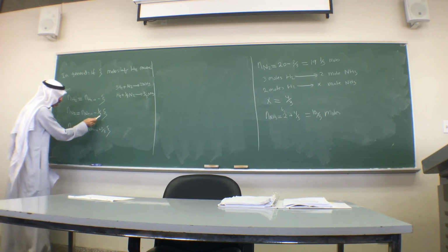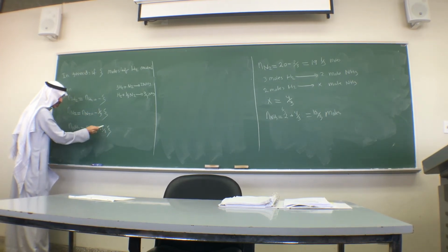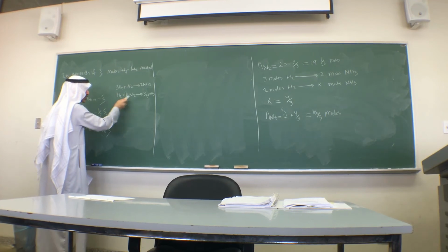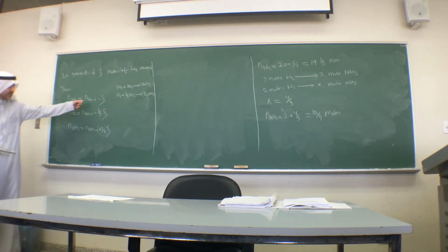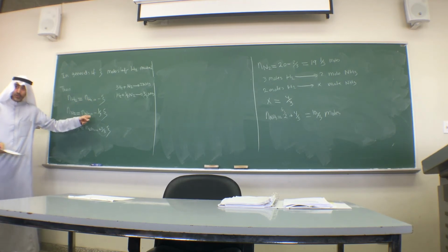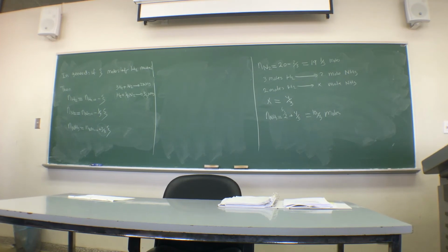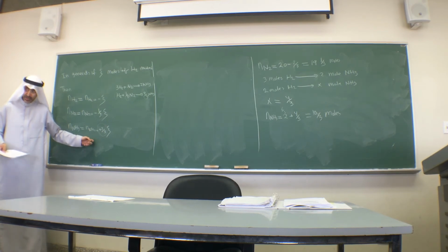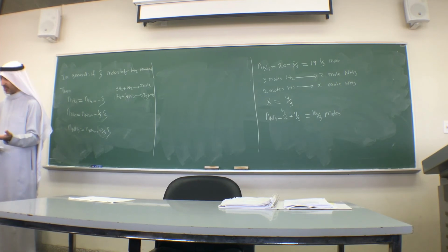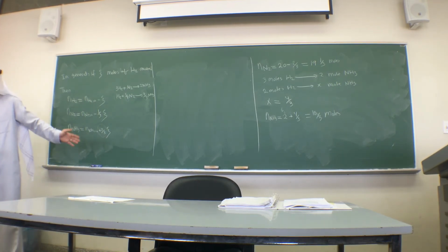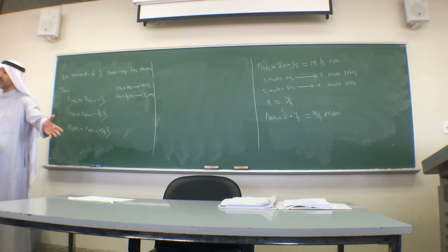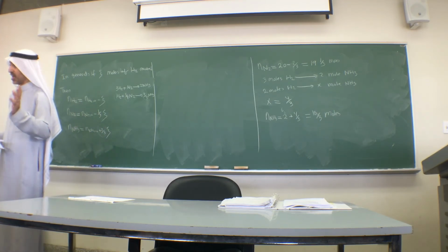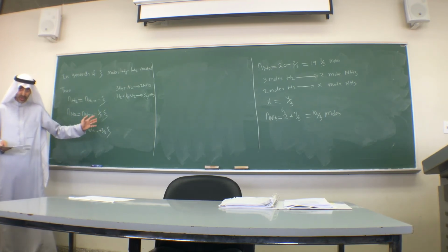So notice something: the coefficient of zeta is the stoichiometry in the equation. If it is a reactant, we put a minus, because with time the amount decreases. If it is a product, it is a plus because the amount is increased. Is that clear, guys? We need this in the method we will use later. They call it extent of reaction. Very important if we have equilibrium, and we can also use it for any reactor. Around any reactor we can do an extent of reaction balance.